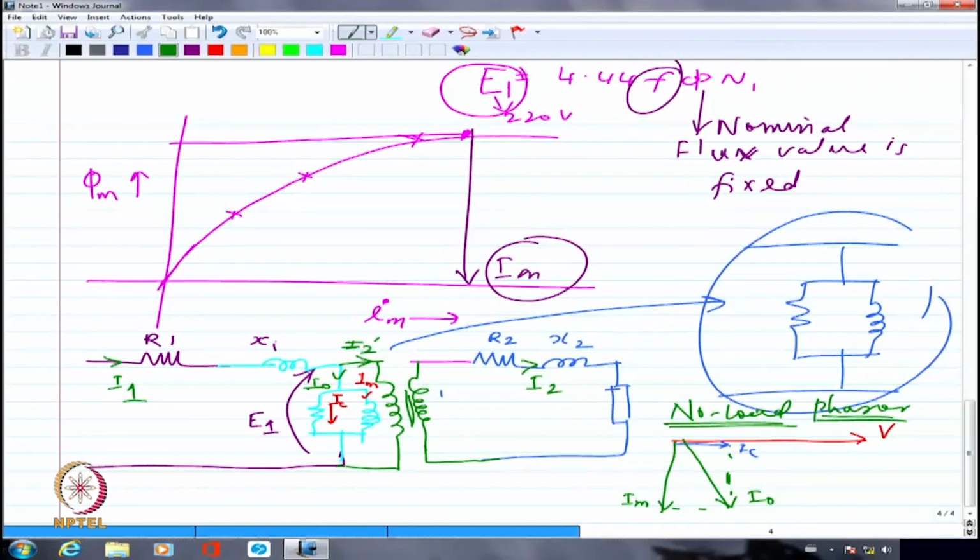But the magnetizing current is, if I look at the comparison, if I have 0.3 amperes as the overall no load current, I may have 0.05 ampere probably as the core loss component of current, whereas almost closer to 0.28 or 0.25, 0.27 something as my magnetizing component of current. So when I add them, I have to say IC is the real component of current. So the no load current will become IC plus j or minus j. It is minus j. Minus j IM.